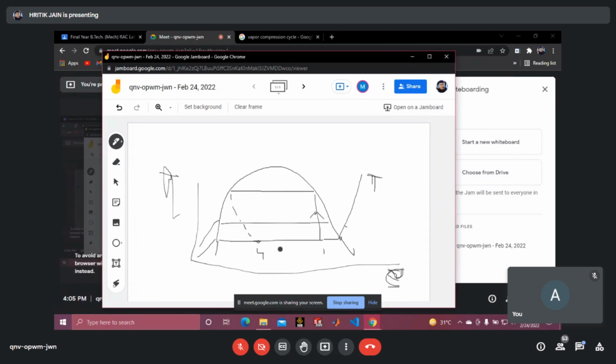For the evaporator or the condenser, am I audible to you now? Whether it is an evaporator or the condenser, what are the techniques through which you are changing the pressure? The one we use here for the evaporator is the heat load. For the condenser, it is the water flow rate. Water is used for condenser cooling, flowing from outside, nothing to do with the refrigerant. So then how does the pressure of the refrigerant get changed?